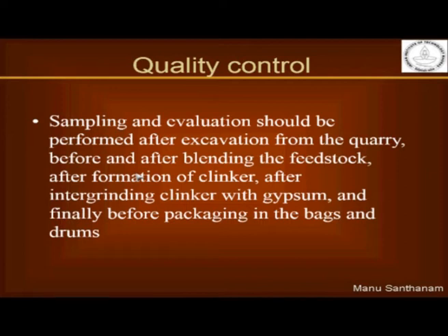And this is why it's very important to understand that you have to use cement in as fresh a state as possible because oftentimes the variability between the batches which are produced in different months may be quite different. So once you have a stock of cement, you have to use it up as early as possible.